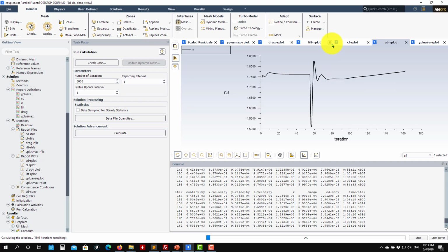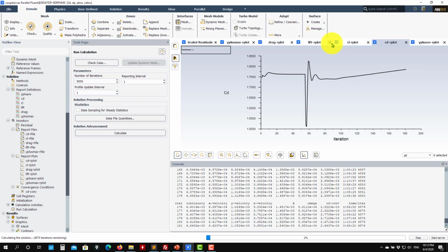Okay, so we're running this one, getting initial solutions, and we're going to see what happens using different solvers, different initializations. So let's wait a little bit and see how the residuals progress, and then we are going to move into a qualitative post-processing and evaluate the integral length scales and refinement criterion.